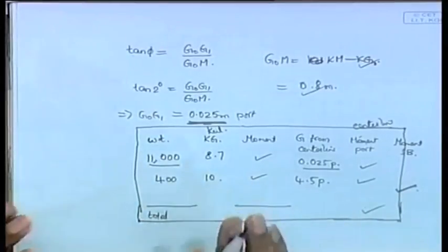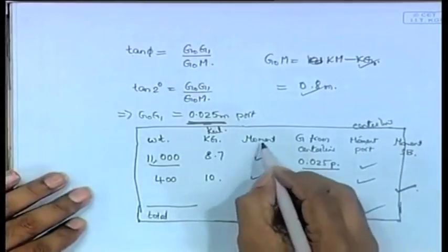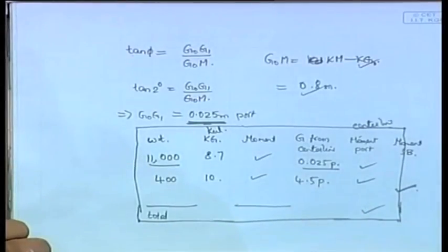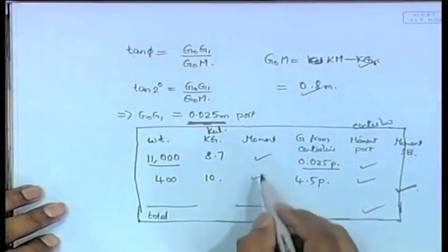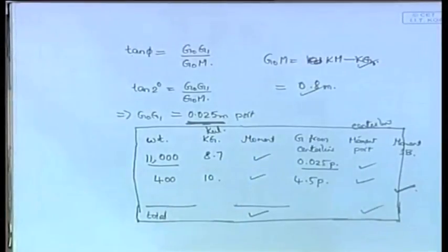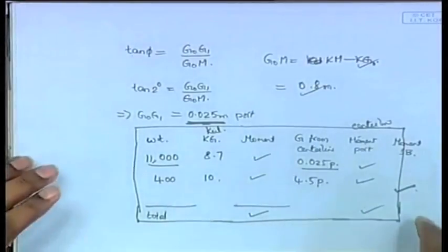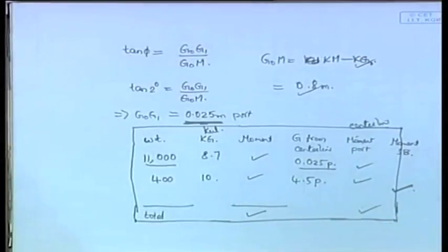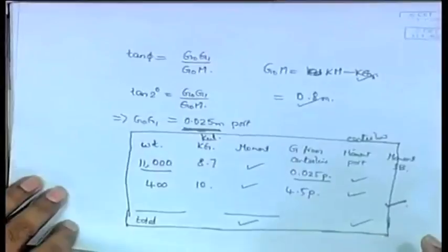This total weight is after all the loads have been added, and you have the total moment here. This moment is to find the kg. That means you have weights at different points, you are just finding where the net acts. So that is kg at different points. This is actually what you are thinking of, we are talking about real moments. It's a vector in that sense. One moment is causing it to heel like this, one moment is causing it to heel like this. We are finding the summation of that, and that much moment is the net heeling to the starboard or to the port side. That is the net.